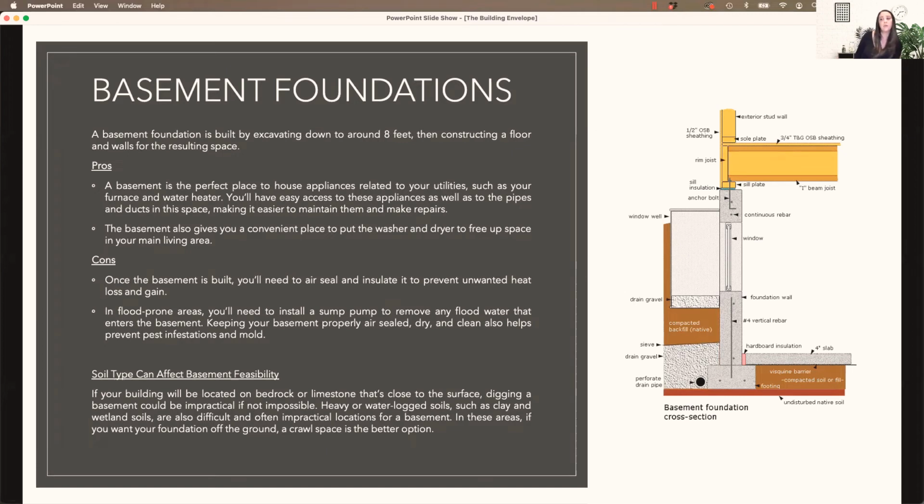I will say that in Colorado, we do have a lot of bentonite in our soils. So we see a lot of soil shifting, and that can cause cracks in foundations and make them structurally unsound. So it is important that all of those soil tests are done ahead of time, and that a deeper foundation is recommended to be dug on the land where it's being proposed.